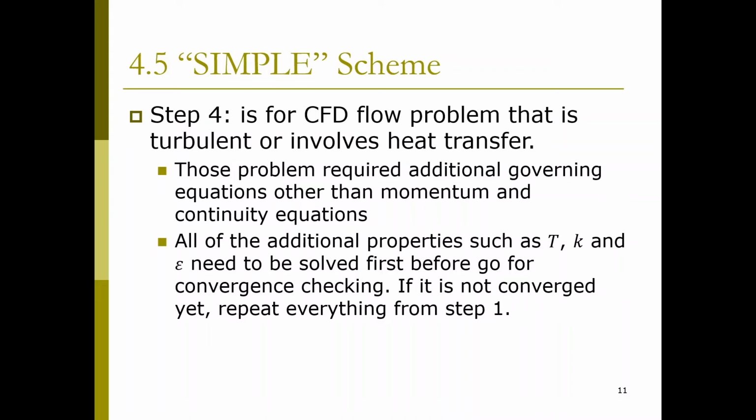So if the flow is not laminar and incompressible, where it has additional governing equations other than the momentum and continuity equations that we use to solve step 1 until step 3, for example when we have a temperature field or the flow is turbulent, we are required to use energy equations, and also we have transport equations, the turbulence equations, which are used to find the k and epsilon, which is the kinetic energy and the energy dissipation rate.